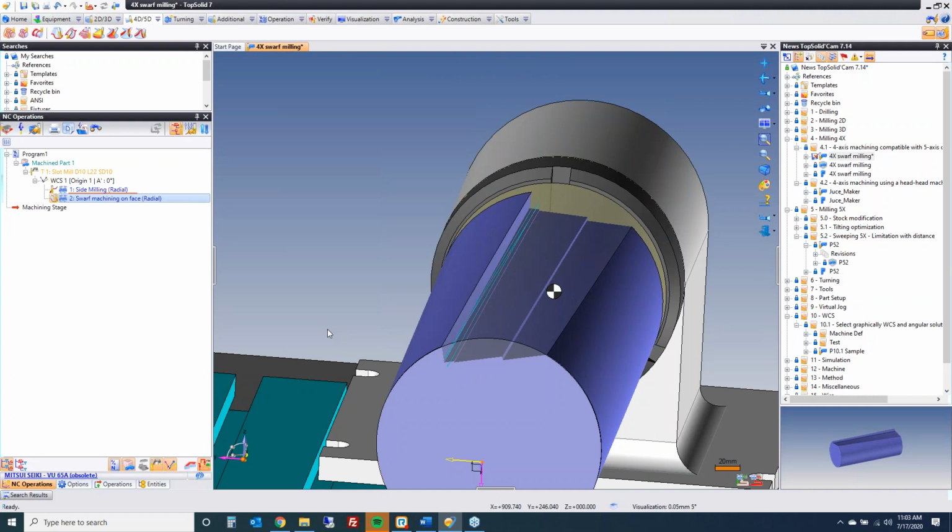So I see your question here, Kevin. It appears that the only thing the side mill operation needs to do is offset the cutter when doing the side milling simulation. It appears to stay constant with the surface. So yes, but as I mentioned earlier, when you're doing true radial machining, the tool has to be perpendicular to the center of rotation, and even offsetting the tool would not cut this specific feature because this feature is evolving, first of all.